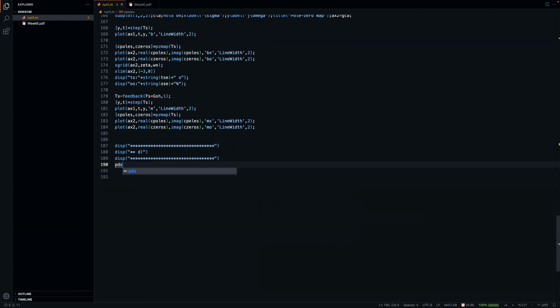But in model matching, since we're at it, since we know what PDS should look like, what we try to do is we try to come up with the ideal transfer function. Usually that's a higher order one when we fix the controller structure, but we forget about the controller for 1 second, and we just focus on the closed loop transfer function that should be obtained ideally.